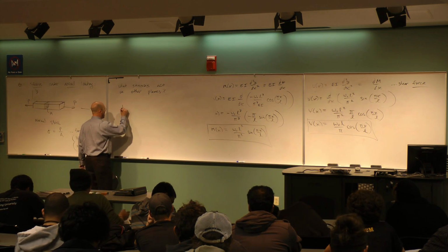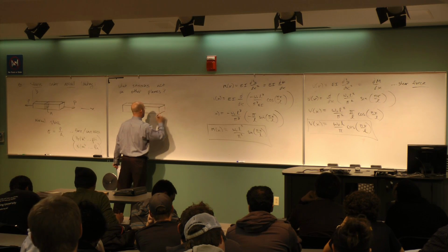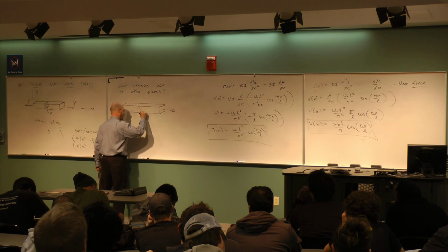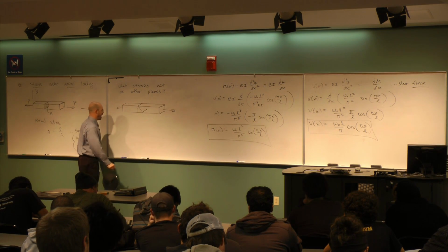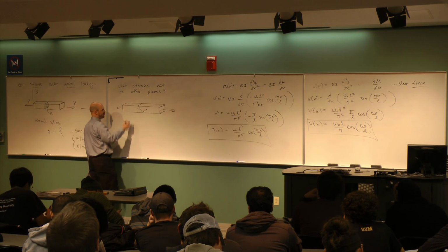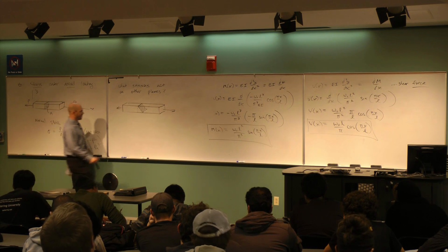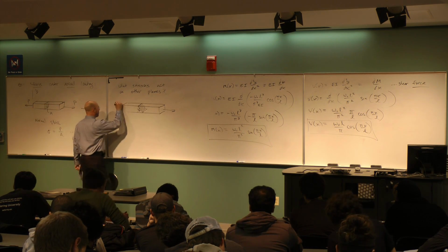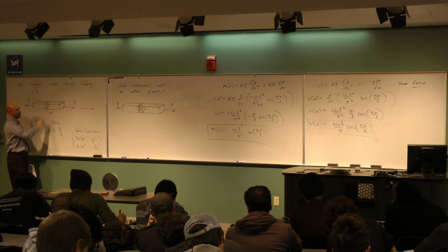But can I worry about it if I take the same bar, and when I pull on this thing now, what if relative to straight up and down, I sliced it this way? Okay, I've got this business going on. Instead of the plane straight up and down, what's the stress acting on a plane that's at an angle like that, where the angle I've cut this at is now an angle theta? Same exact bar, same loads P. Now I want to think about theta that's not straight up and down, but goes like this.